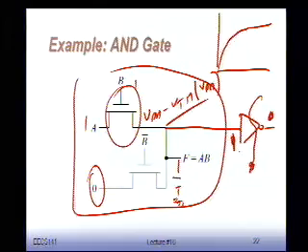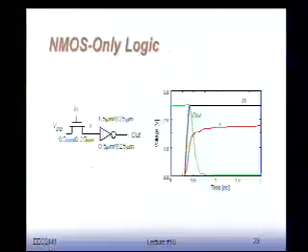As a result, this PMOS device is not only going to be at the edge of on, but actually it's going to be on. And this becomes a leaking device, a pretty badly leaking device. So that's a challenge. That's the big problem with NMOS-only networks, definitely if you follow them with this inverter type of reconstruction logic.